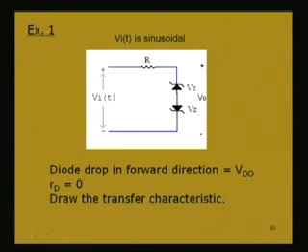So, today we have seen a very important application of normal as well as Zener diodes along with resistance and capacitance to build circuits known as clipper and clamper. These circuits are used in practical applications where we want a waveform having one portion clipped off, or clamping the level of the DC voltage of the waveform at some other value than what it is.